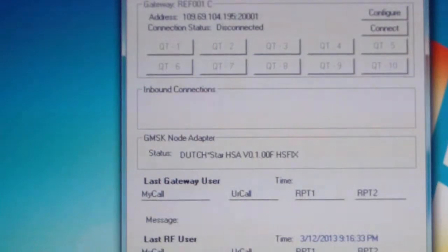I'm not exactly line of sight to where I'm at work, and thus far on 2 meters I have been able to receive and listen at work on the HT, but I haven't been able to get back in. So I've had it running 50 odd watts from the base, projecting out, so that's obviously why I could pick that up and receive it, but going back in I wasn't able to get back in with the 5 watts in the HT. Obviously I expect that to be different when I start operating mobile and can push the power there a little bit and have a better antenna.